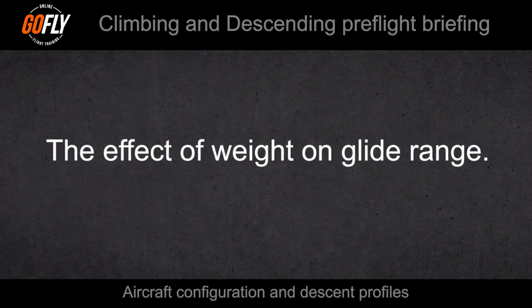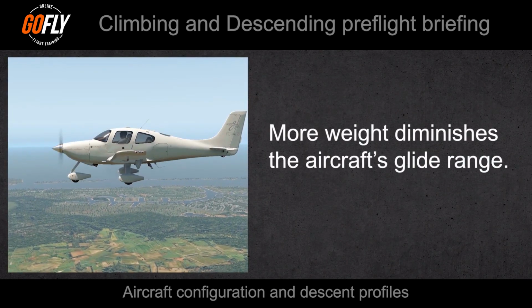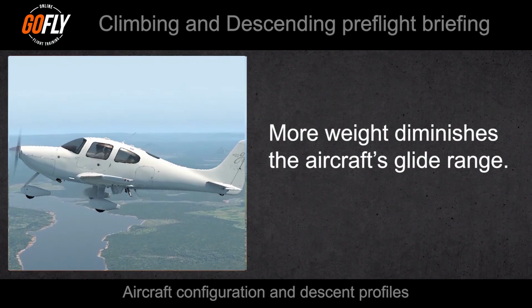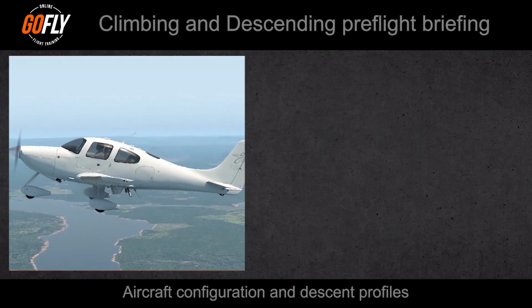As for weight, the heavier the aircraft, the more lift is required to balance the force of weight. The extra force required means for the same airspeed, more angle of attack is required, which results in more drag and therefore diminishes the aircraft's glide range.